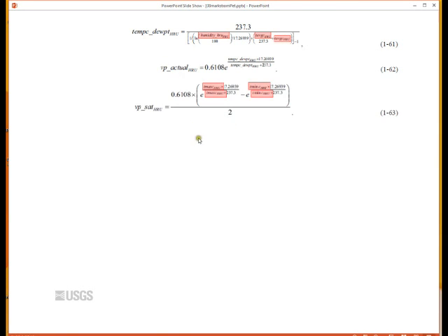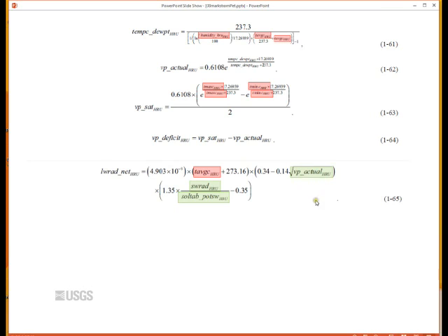Then the final one is the Penman-Monteith formulation. The final equation is going to depend on dew point, so you actually have to input the humidity per HRU. You have to input the temperature, come up with the actual vapor pressure. We need the saturated vapor pressure. That can be computed from the temperature on the HRUs. Subtract those 2 and you get the deficit, which is what the equation is going to use.